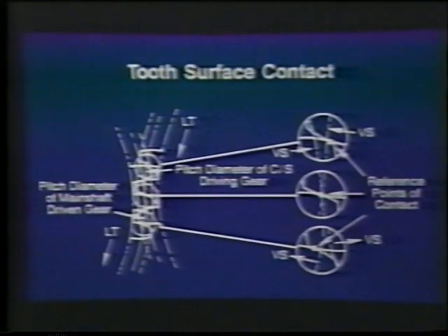The engine's power is transmitted between gear teeth in a sliding motion, then a rolling motion, then sliding again as the gears rotate. A thin film of lubricant is carried through mesh to prevent metal-to-metal contact. Because most loading occurs at full mesh, gear tooth profiles are designed to minimize wear caused by sliding motion.